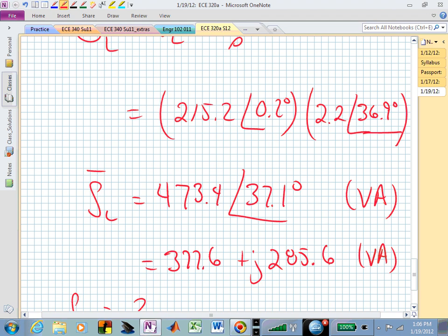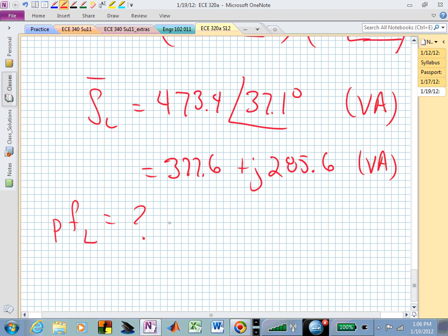So you could find the angle of that impedance and take the cosine, and that would give you the power factor of the load. What we had also talked about was that it's really the P of the load over the apparent power of the load, which was V sub L I sub S. Is that hanging out anywhere?